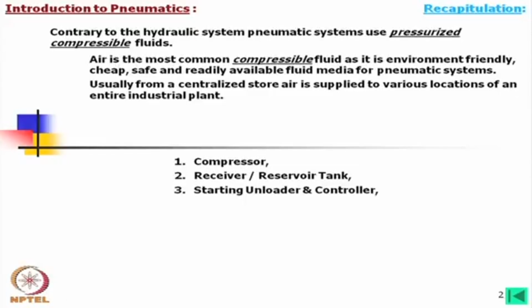Then, the compressor, as you know, cannot run continuously, and it is not desired that it would run continuously. So there is a system by which the compressor is stopped when the compressed stored air reaches a certain upper level of pressure.